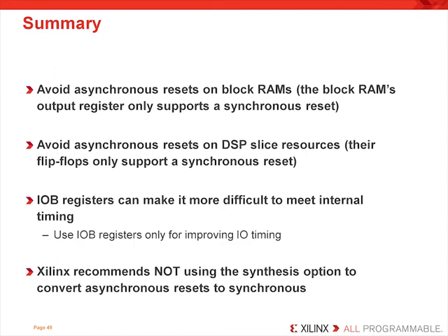So let's take a minute now and review some of what we've learned in this recorded e-learning. Avoid asynchronous resets on block RAMs. That's because the block RAM's output register only supports asynchronous reset. Avoid asynchronous resets on DSP slice resources. Again, their flip-flops only support asynchronous reset.